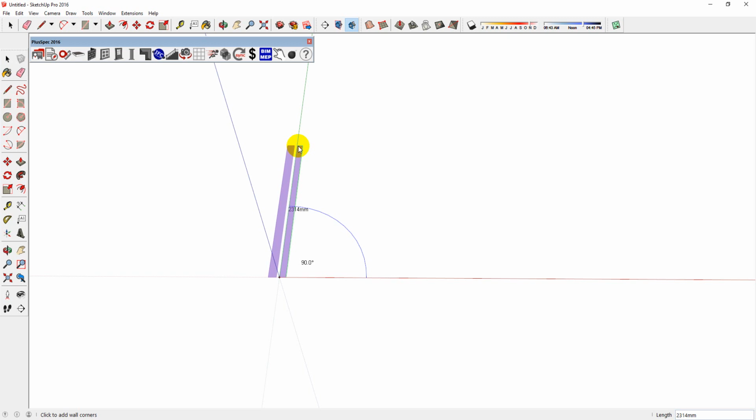However, if you start drawing anti-clockwise, that's not a problem, because you can click the Insert key on your keyboard to flip the wall orientation. See how it's changing? If you are using Mac, press the minus key near the Delete key. Always ensure that the exterior of the wall faces outward, because once you have finished drawing, there is no easy way to flip it.